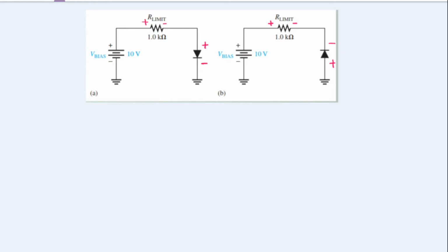Our first circuit consists of a power supply, resistor, and a diode. When the diode is operating in the forward bias zone, it must reach the specified threshold voltage to pass current. Generally, this value is around 0.7 volt for silicon diodes and 0.3 volt for germanium diodes.